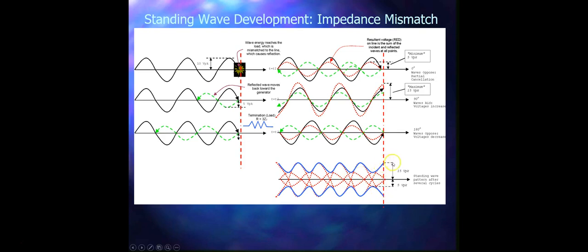Here the 15-volt peak voltage value is given, and on the negative side the peak is 5 volts. These standing waves you see are basically the outgoing and incoming waves meeting each other and causing their voltages to add at some points and subtract at others. The result is our standing wave, which is normally not what we actually want in our transmission line.